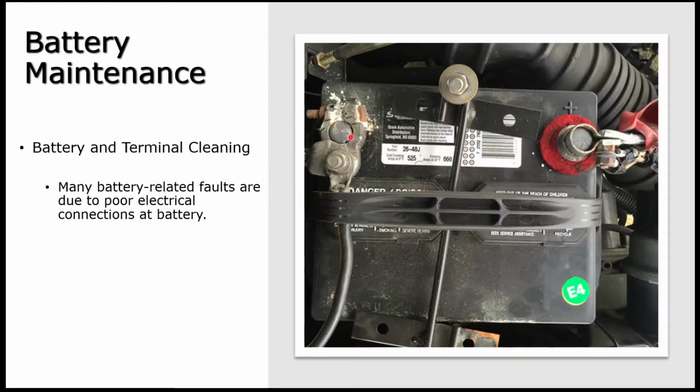So we have a bad corroded connection on the ground side. We have a loose, improperly fitted connection over here. What's happened is that this terminal has expanded and it too needs to be replaced. The reason being, if you look at this right here, you can see that this is completely down as tight as it will go. And you'll also notice that these nuts are corroded a little bit and kind of in rough shape.